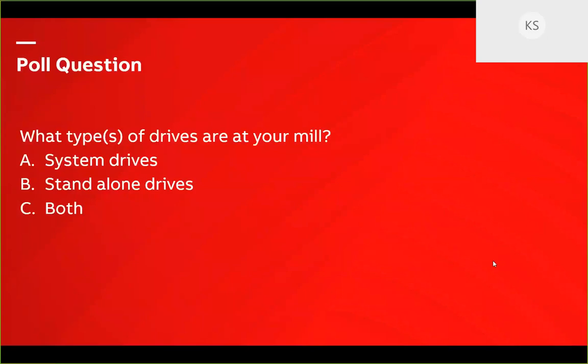Yeah, sure. A system drive would be the sectional drives on a paper machine or tissue machine, winder, re-reeler, coder, on machine, off machine coder. Standalone would be pumps and fans, also maybe recovery boiler, line kill, things like that. So the system drives, sectional drives we'd call zone 1, and process drives, standalone throughout the mill, we'd call those zone 2. All right. Well, thank you.